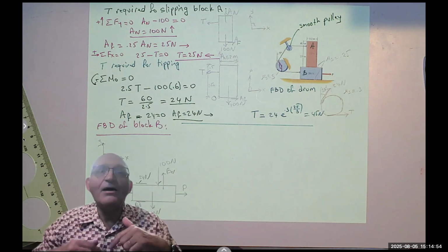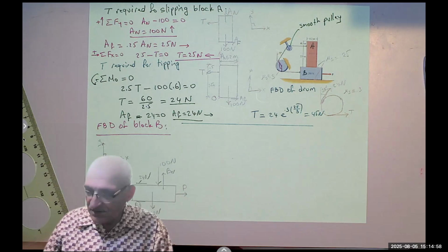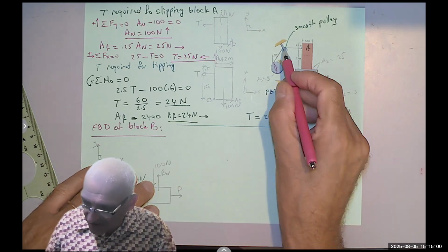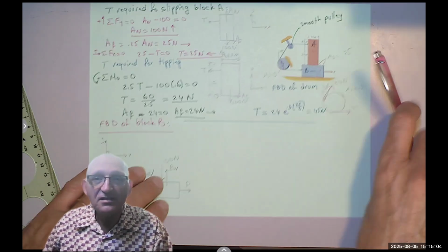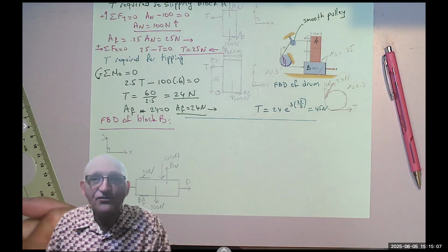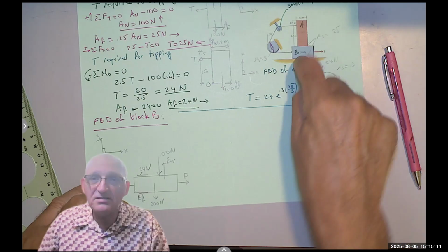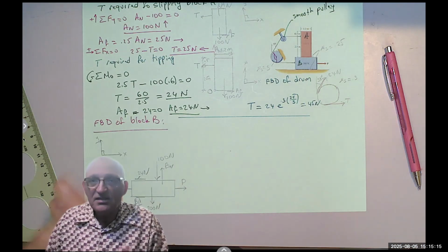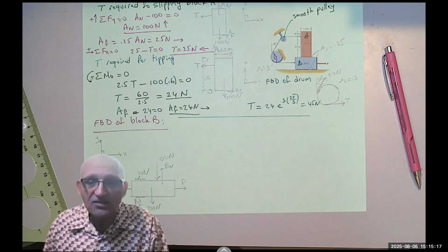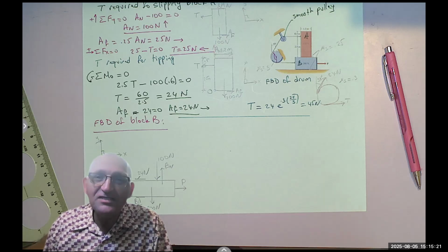And all the outside forces acting on the blocks are horizontal. This cable is horizontal, this cable is horizontal, and you are applying a horizontal force. So that's the only time my B sub n would be 300. I don't need to do any math. I know the weight of the blocks is 100 and 200, so Bn is 300. But it is not always true.